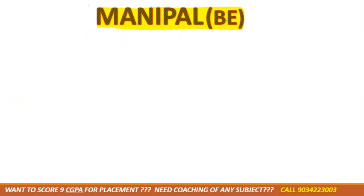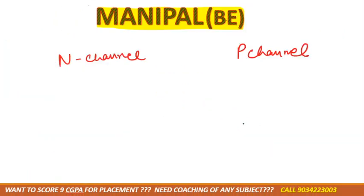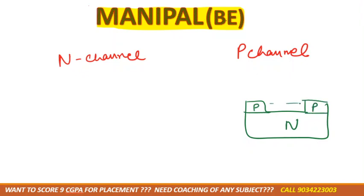like the symbol of this one. As I told you, MOSFET is divided into two parts. One is N channel, another one is P channel. The diagram which we have done was for the N channel, because we have formed an N channel. If I take it opposite, meaning if I take the body as N type, then I'll do the doping of P channel and form the P channel. OK, the symbol, write it down.